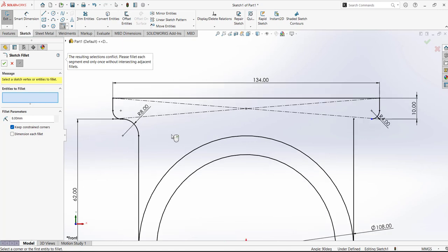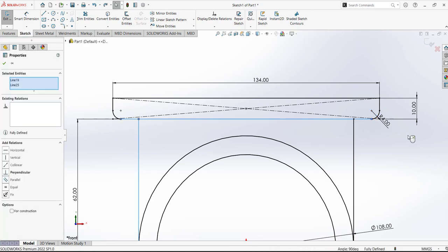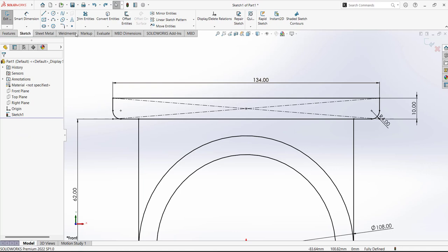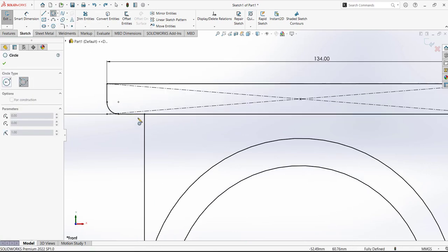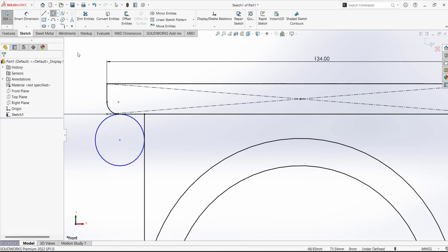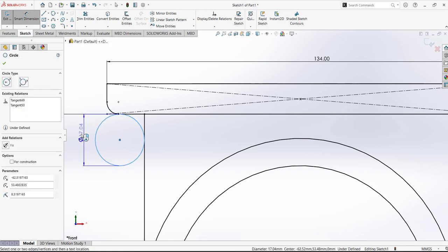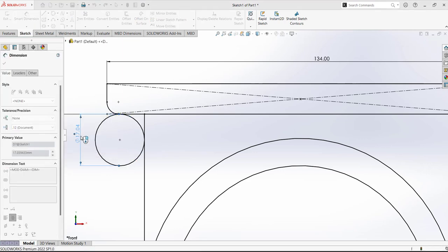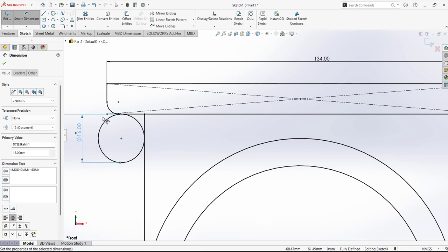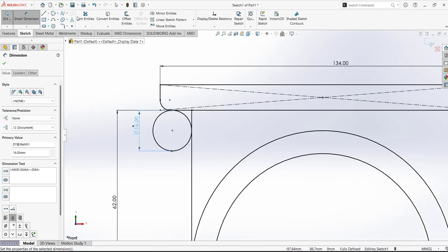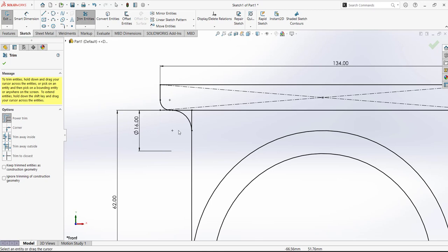You can see if you go and select the fillet command for these two intersecting lines, it is trimming the lower side of the rectangle. So we'll undo it and again we'll go for the other option, that is perimeter circle, so as to avoid the trimming of this line. This is the alternate for the fillet command. We'll put up the value here as 16 as we are defining the diameter, but the radius was given 8. It is equal only.